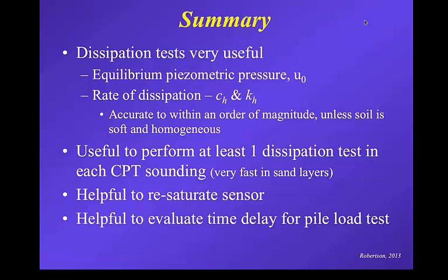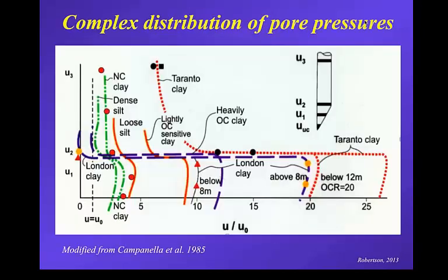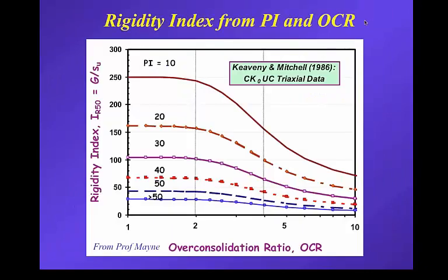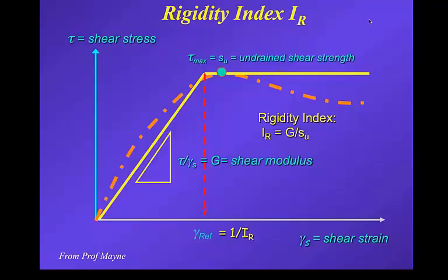And so the red line is matching the theory with the measured. You can see it matches pretty well, but down around the T80 and T90, it's not matching so well. So in this particular case, it would really illustrate that using T80 or T90 wouldn't give you the same answer as the T50. The reason people have homed in on T50 is twofold. One, of course, you get there faster, about 30 to 40 times faster than it will take to get to T80 or T90.